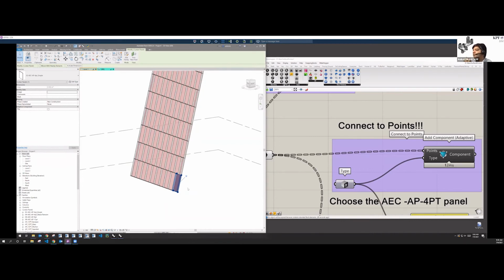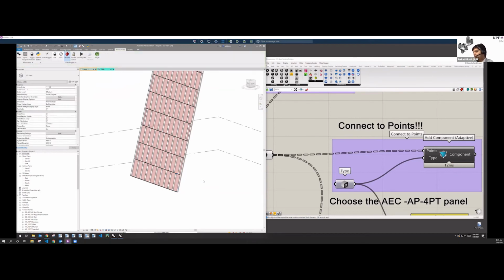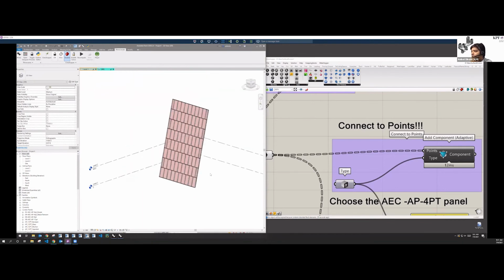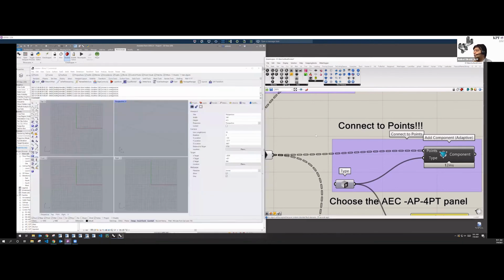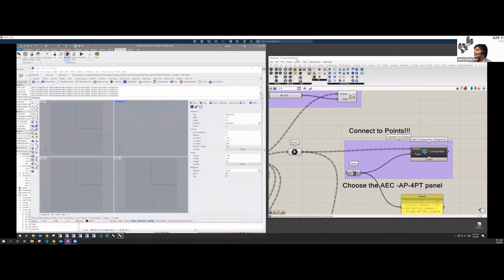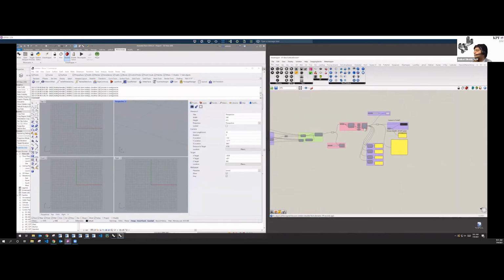But for the same session, if your geometry is pinned, then everything inside of that geometry is still being controlled by Grasshopper or Rhino.Inside. If it's not pinned, then everything is free to go and you can modify it. So if I unpin it, I can move that around if there's a need to fix something specifically in there. So that's pretty much how you place a very basic curtain wall panel inside of Revit.